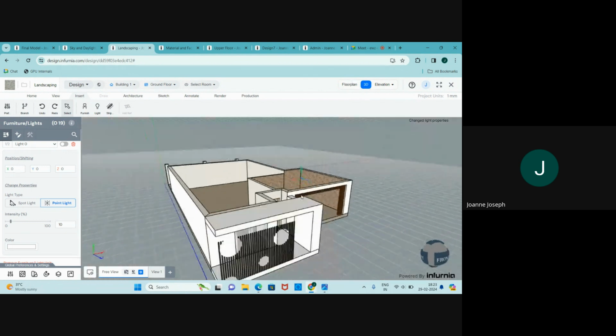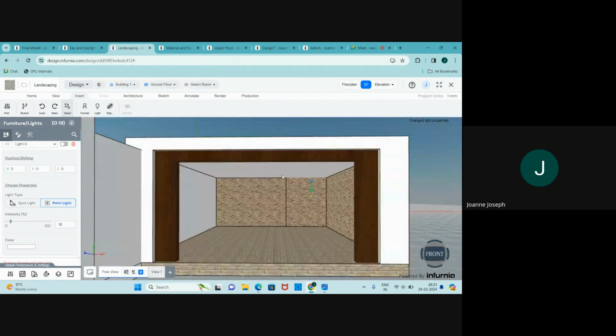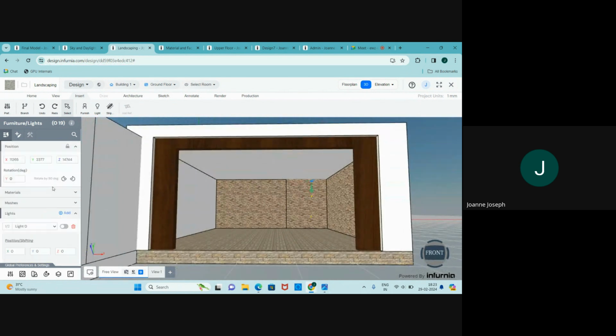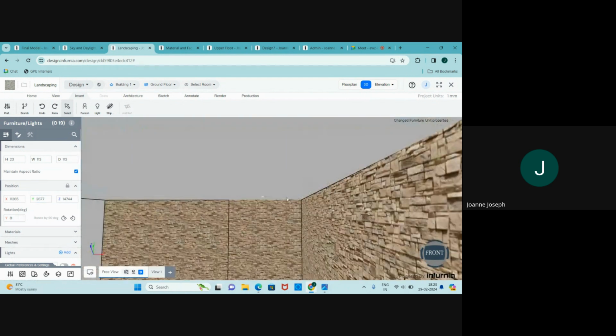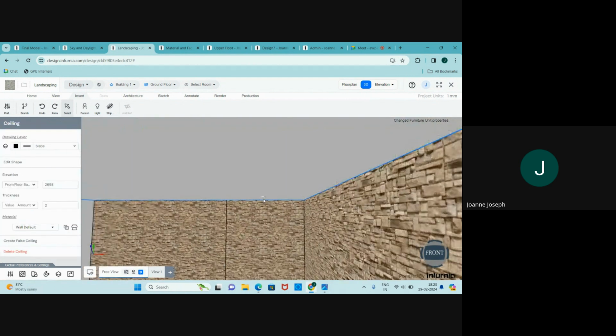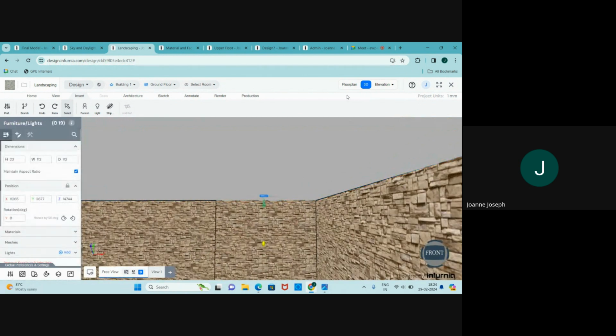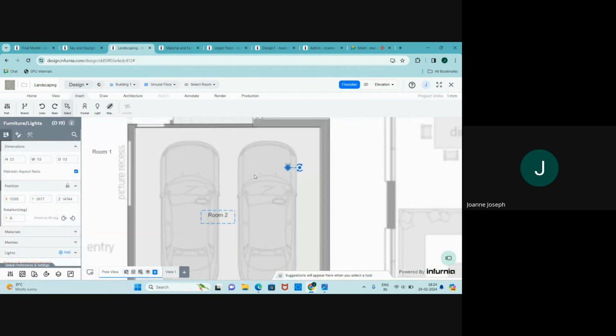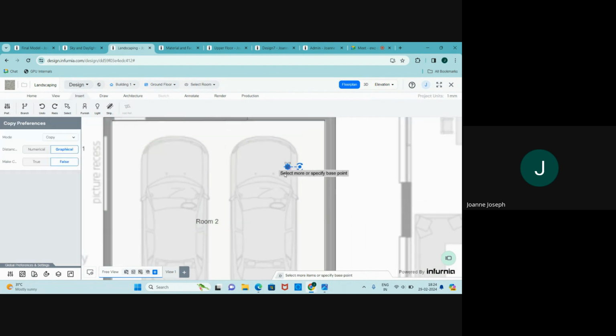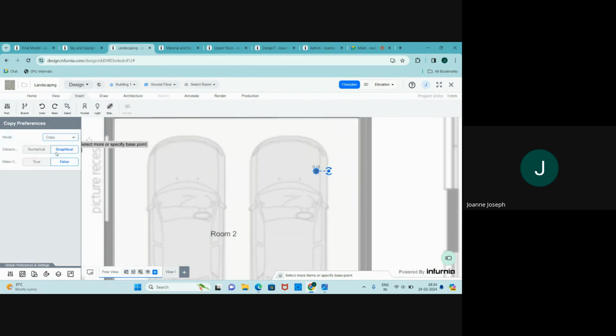And in 3D as well, I can set the elevation by going up on the left-hand side and typing in, experimenting with the elevation here. Now, once the elevation is set, you can go ahead and copy these everywhere, because later you will not be able to change the elevation for all the lights. You'll be able to only change the intensity for all the lights. So always make sure the elevation is set properly before you proceed with the rest.